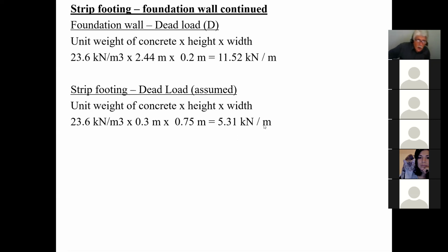So now I've got all my loads coming from the roof all the way down to the soil, because that's what you have to calculate in order to calculate the size of the footing. In other words, you have to calculate all the loads coming down. And don't forget, when we calculated the isolated footing, we forgot to add the weight of the footing itself, and I should go back and check to make sure that that 3 foot by 3 foot is sufficient.